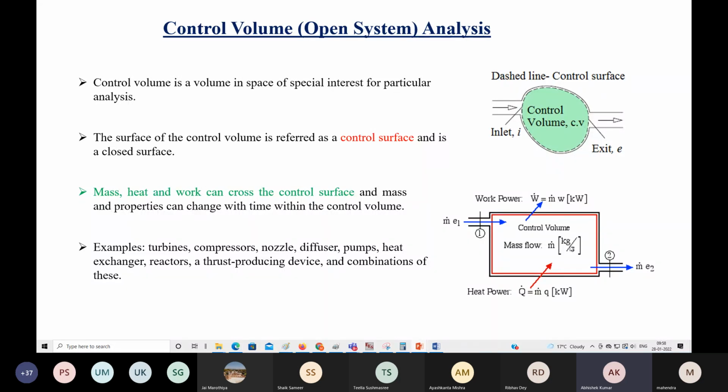That steam, saturated or slightly moist steam, is leaving to the condenser in case of steam turbines. In case of gas turbines, hot combustion products from the combustion chamber come over here and expand in the turbine blades. Because of that, pressure energy is converted to kinetic energy in the blades, and that is developing the work.